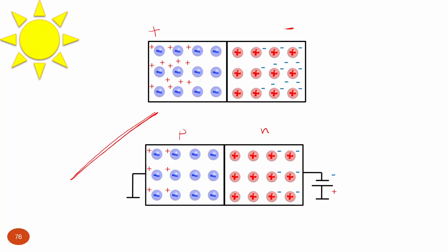So from here we see that there is a correlation between a p-n junction in the dark under forward bias and a p-n junction under illumination without any bias. It just creates this bias because of excessive negative charges at the edge of the n-type region and excessive positive charges at the edge of the p-type region.